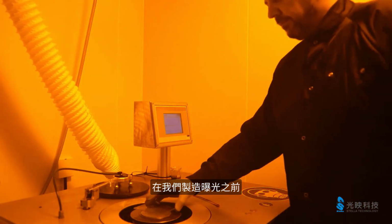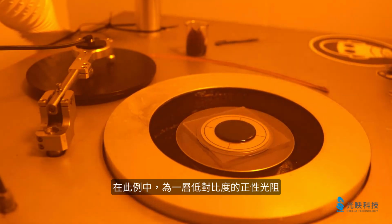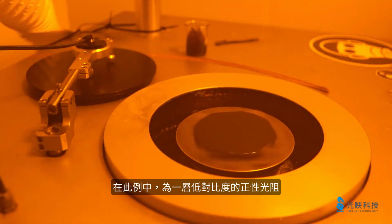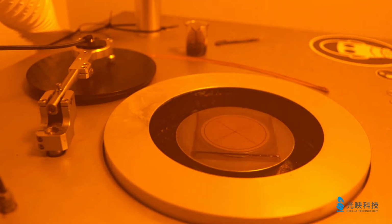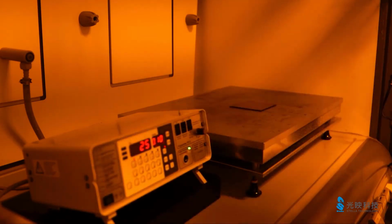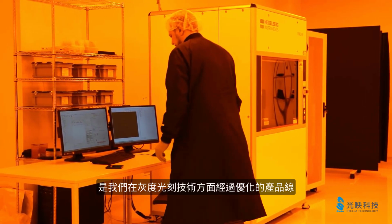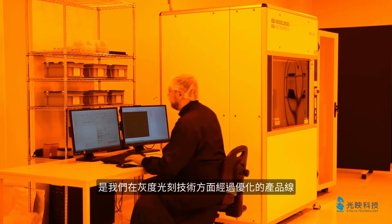Before we can make the exposure, we need to coat a substrate with light-sensitive photoresist, in this case a low-contrast positive resist, followed by a heating step to evaporate the solvent. The Heidelberg Instruments DWL series is our product line optimized for grayscale lithography.